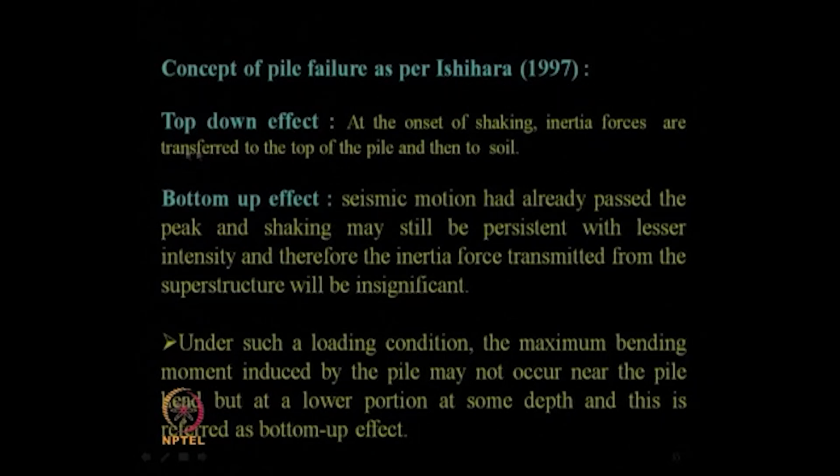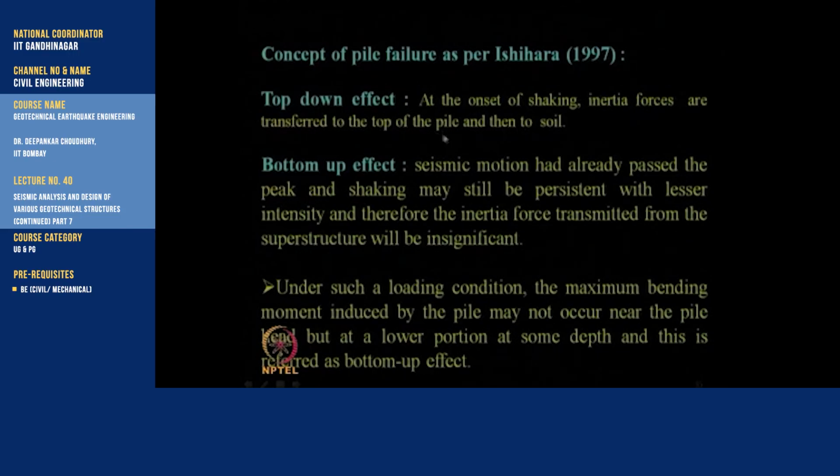He gave the details about two basic concepts. One is called top down effect, another is called bottom up effect. So, what is top down effect? At the onset of shaking, inertia forces are transferred to the top of the pile and then it goes to the soil. So, this is one way of approach of analyzing it.